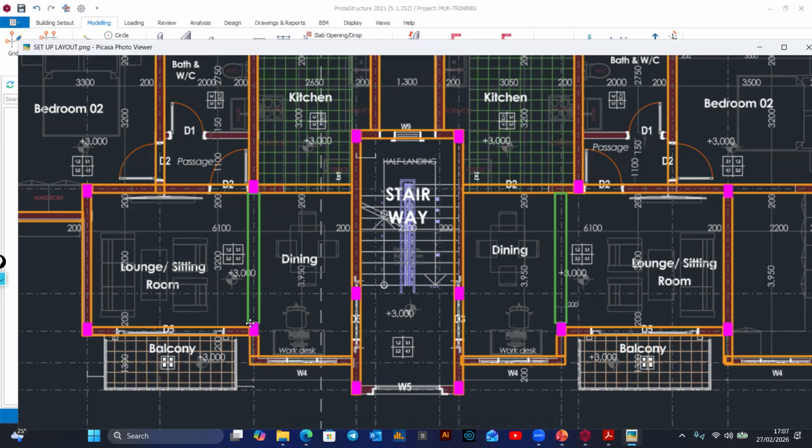But that is the principle; at times, depending on how your ribs are going to run, if it's going to be a rib slab, you might find that in some cases the concealed beam has a bigger cross-section area compared to the drop beam because it takes a lot of reinforcement. You get it?